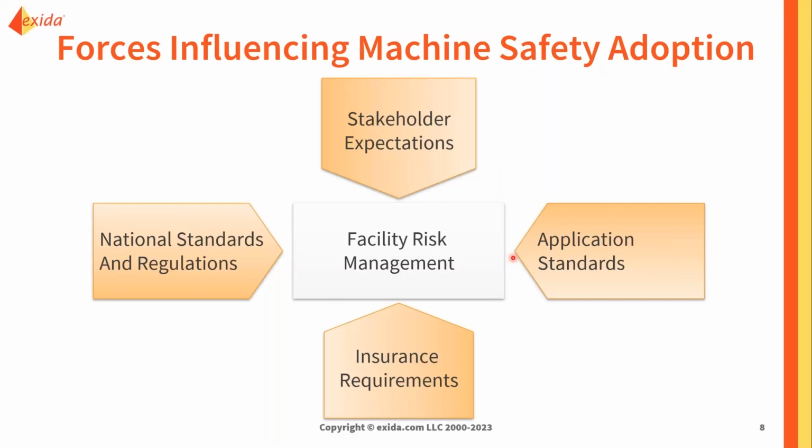And then lastly, on the machinery side, there are a lot of application standards, different types of standards, from more general broad categories such as ISO 12100 for risk assessment, or looking at 62061 and ISO 13849 for how safety systems or safety-related control systems are implemented, as well as some very specific application standards to specific safety function types, specific machine applications that we'll talk about a little bit more, but those can be very helpful for identifying specific steps as well.